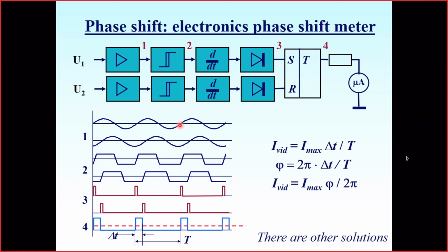So with our initial signal, we transform it into a signal where we have pulses every time our waveform crosses zero and grows. Actually, this circuitry is one-to-one the circuitry used for the synchronization of oscilloscopes. They use the same circuitry.